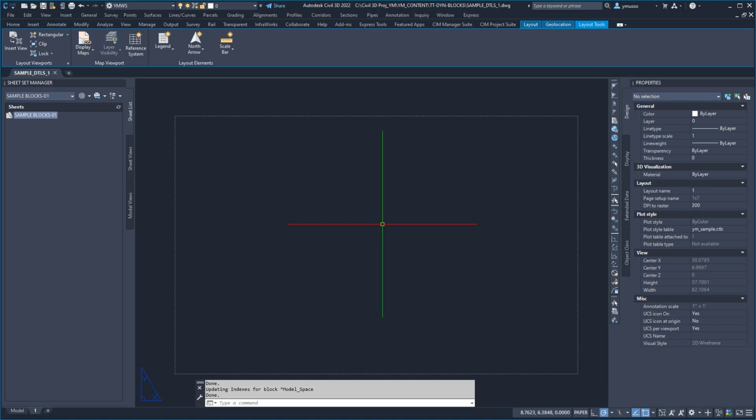Blocks are one of the most important object types in AutoCAD, and they are used often. Blocks are a collection of line work, images, and text that acts as a single object, and unlike the group command, you can assign an insertion point used frequently throughout the drawing and can be shared. Many organizations have adopted the use of blocks and have invested time to create their own set of standard blocks. They help keep consistency in the project drawing and avoid recreating the same object, a huge time saver.